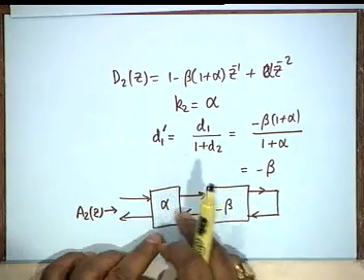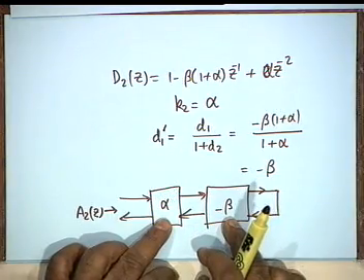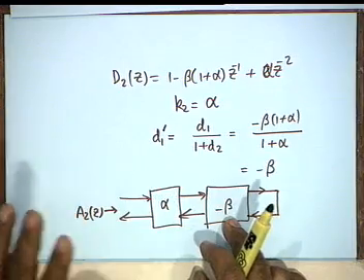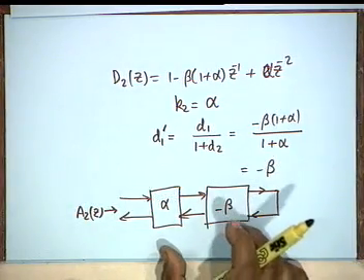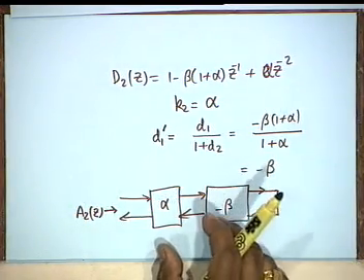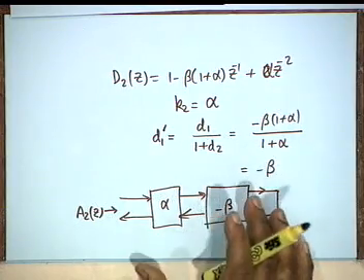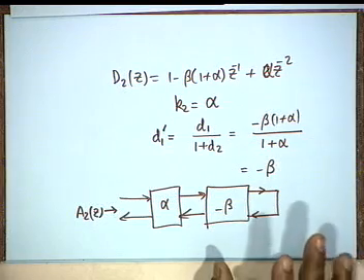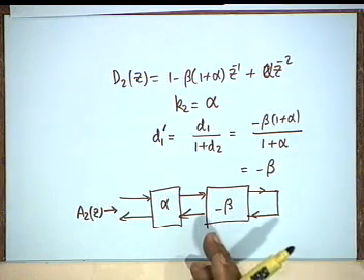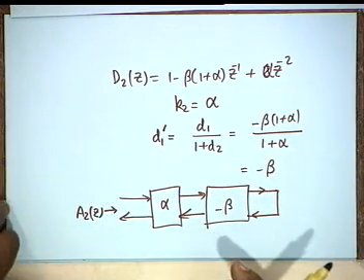That is, when you change alpha, the center frequency does not change. This is the ideal situation. It is very difficult to attain this in analog filters. Digital filters totally isolate the bandwidth control and the center frequency control, and this is also available as a commercial chip.